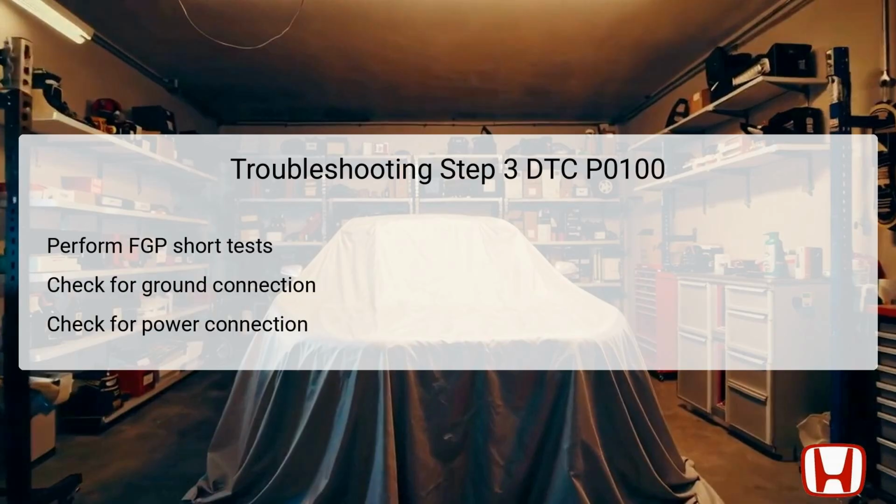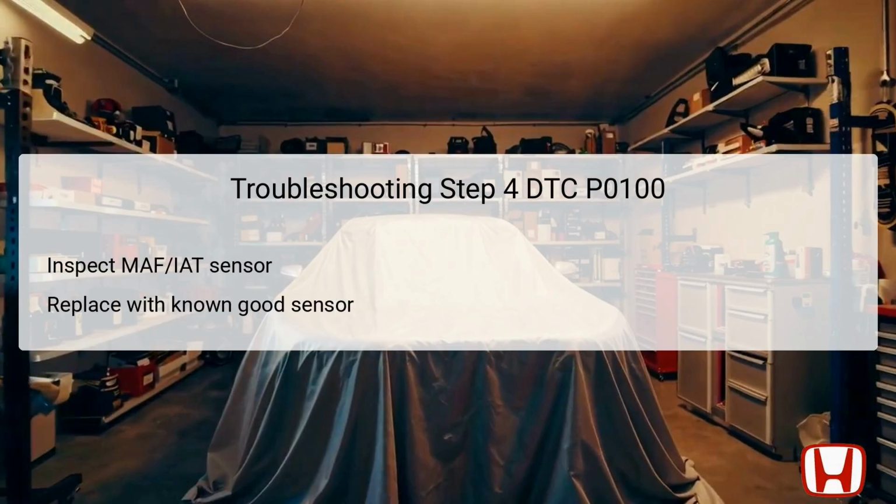Conducting these tests helps in diagnosing the state of the circuit and determining whether the MAF sensor is functioning properly. These checks link back to the DTC P0100, as faults in these areas can directly lead to low or absent MAF sensor signal frequencies that prompt the error code. Next, we turn our attention to the MAF AIT sensor itself.